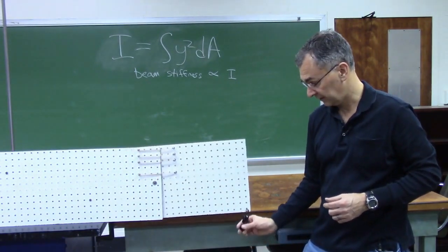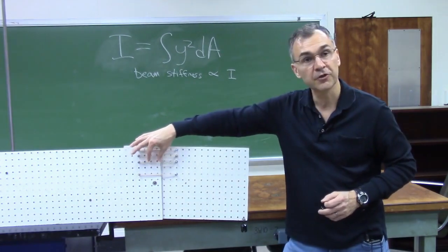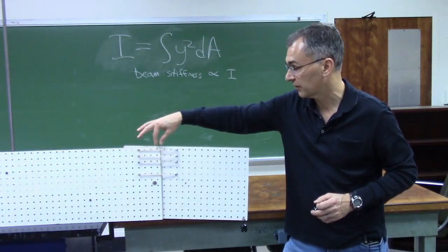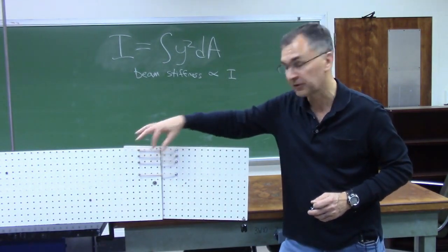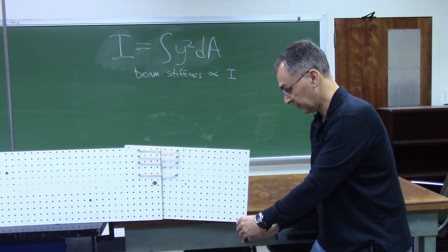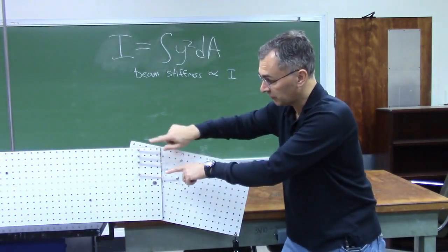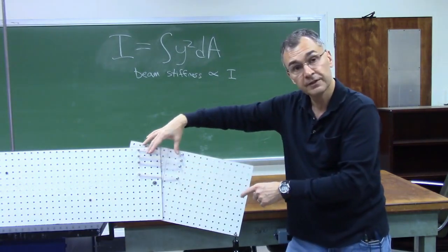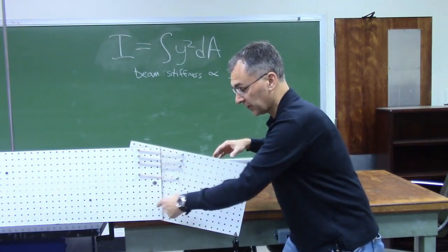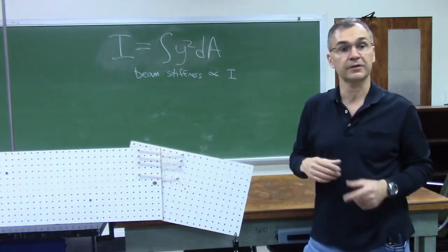And if I subtract this weight, then a smaller torque is needed internally to counteract that, and therefore each fiber stretches less, producing a smaller Hooke's law force. And then I make the load larger again, and we get a clockwise torque caused by this weight, and then there's an opposing counterclockwise torque caused by this tension. In a real beam, there would also be a counterclockwise torque caused by this compression, but we don't have any springs here in compression to illustrate.